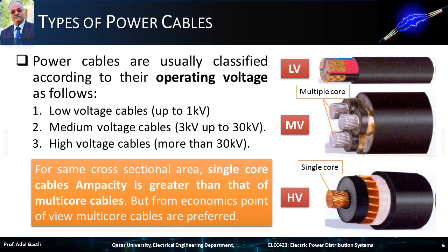Disadvantages of 3-core cables are that individually the cables are larger and heavier than a single-core cable, which limits the length of the cable that can be installed on one drum, before it exceeds vehicle height and weight. Manufacturers also have a limit on their drum twisting capabilities to lay up 3-core cables. The maximum conductor size of 3-core cables is thus lower than single-core counterparts, requiring more joint bays on a long route. 3-core cable joints are more complex than single-core joints.